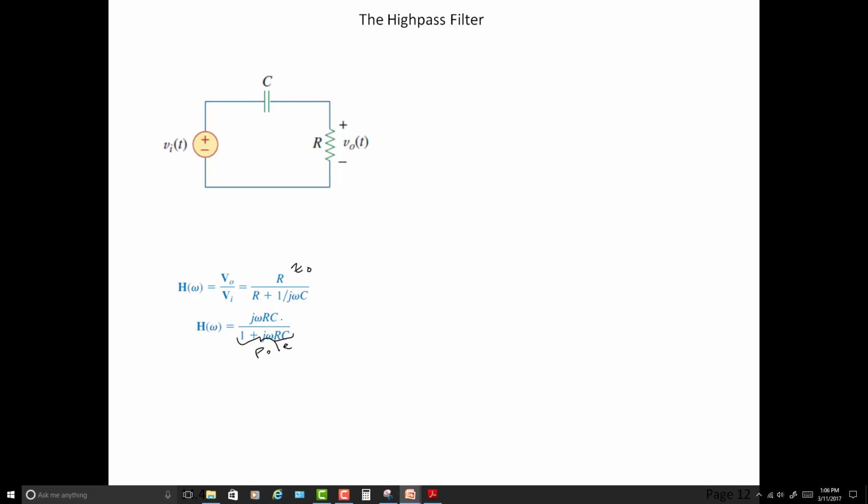But now we've got something else, a frequency component going on in the numerator. So we have a 0 at the origin, right? You'll also see a phase difference too, but all of that is to be expected, right? Because if you just do the vector pictures like I did in the last one, you'll see more of the same going on. So it's no surprise the corner frequency is going to be identical because we have a pole in the same location.